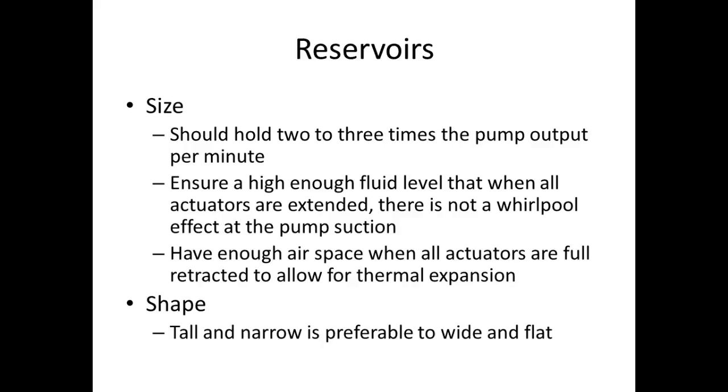Have enough airspace when all actuators are fully retracted to allow for thermal expansion. So this is going to determine the size of your tank. When you extend all of them, they create a whirlpool. When you retract them all, you fill it up so it doesn't do that, but then your tank overflows. So it's going to be somewhere in between. Tall and narrow is preferable to wide and flat.